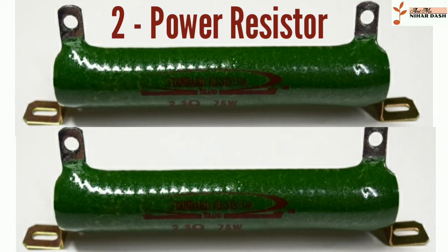Some are wire-wound, some are made from wire grids for ease of cooling, but the common thing for all power resistors is that they are built to dissipate the most power while keeping their size as small as possible. An example use for power resistors is load banks used to dissipate power generated during engine braking in vehicles using electrical motors, such as locomotives or trams.